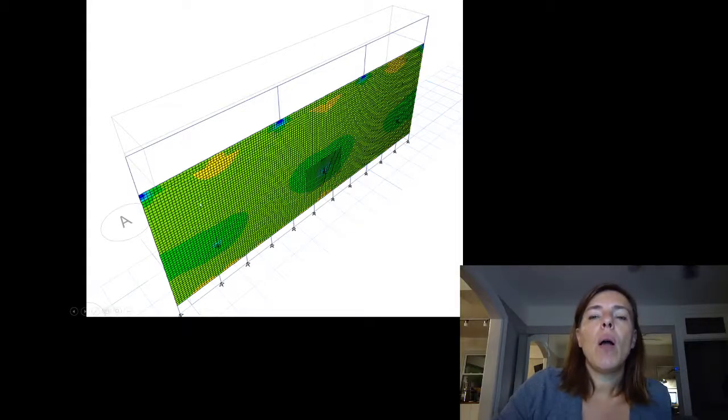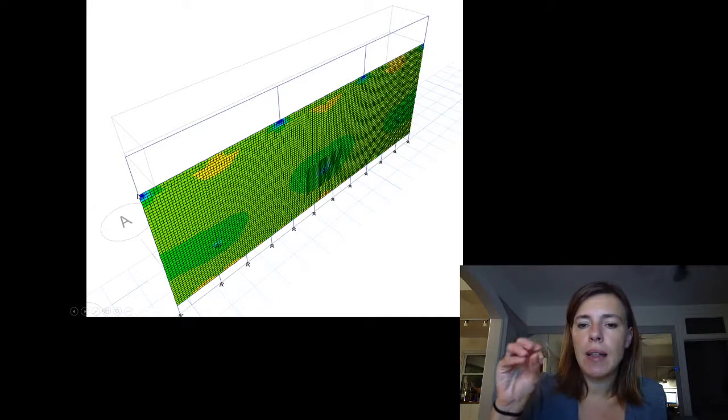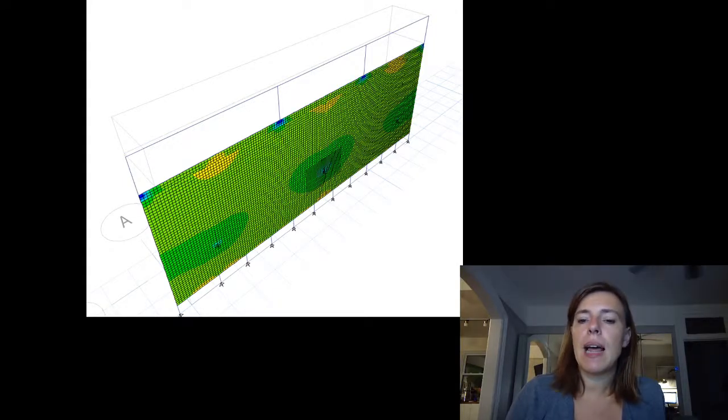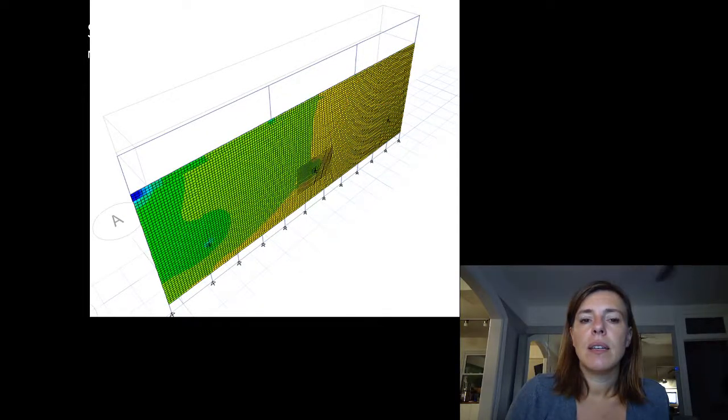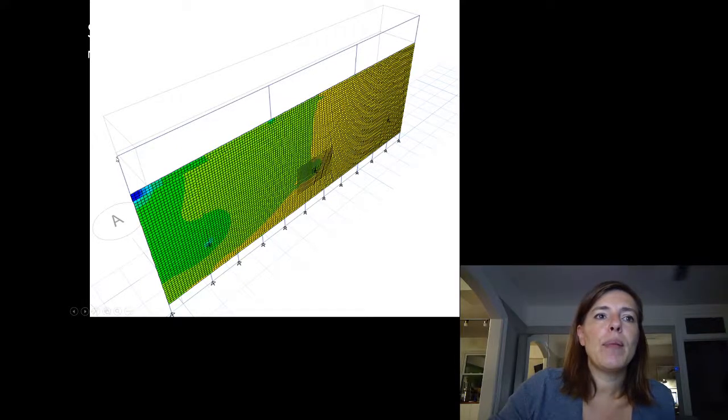And then I wanted to look at the worst case spots and see, as I broke down the analysis, or basically became finite element analysis, what those stresses were. And if they were reasonable and less than what we would expect from the basic taller glass guard, then I was okay with it. So this was one load case. Here was another load case. You can tell this one was probably from the 1 kilonewton point load added right here, where my worst case stress was right here.